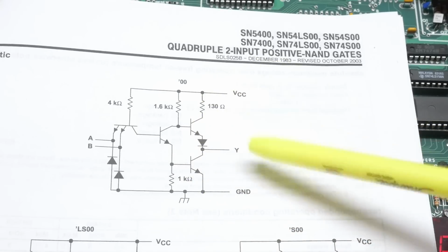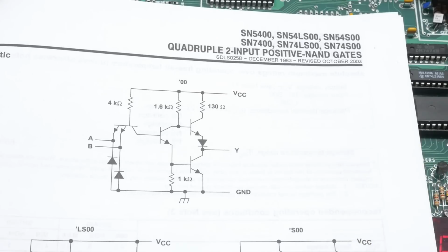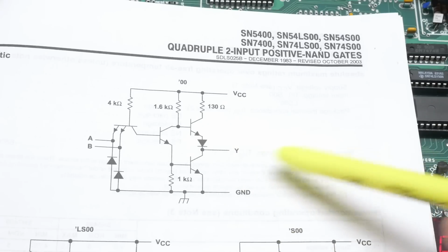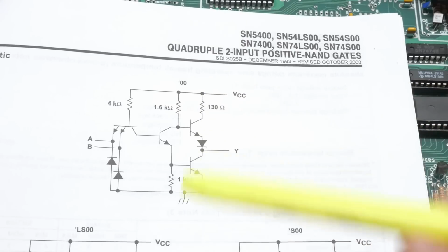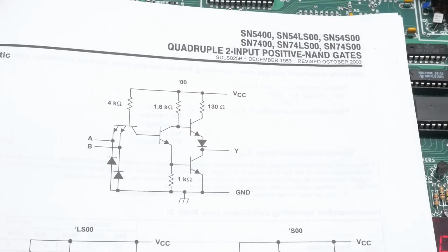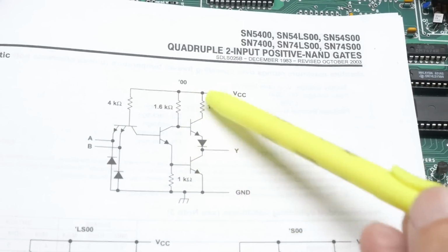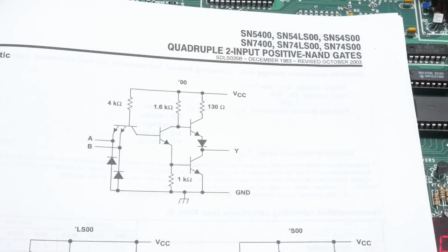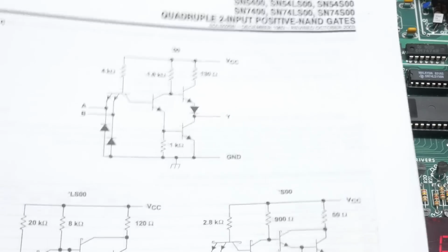But look at the upstate. It goes through a diode, and then it goes through a transistor, and then it goes through a resistor. So it doesn't pull up very good. And as you start loading down the input, it really can drag this down. So you can never quite get to VCC. It's got all this stuff in the way. But that's just the way it was back then. And things just weren't great. Let's take a look at some of the numbers in the data sheet.